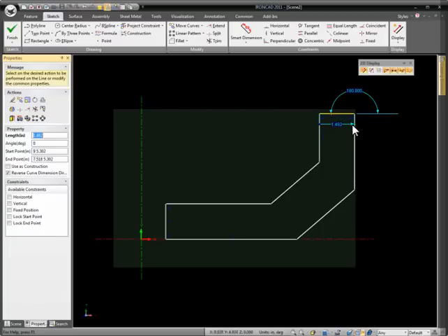Notice our arrow is pointing to our right. Well, we don't want to move our outside dimension. We want to move the other side. It's a simple operation. Notice if you select either side of the curve, just think there's an imaginary midpoint. You pick the opposite side of the curve, and the arrow will change to give you a different direction of that curve when you edit it.